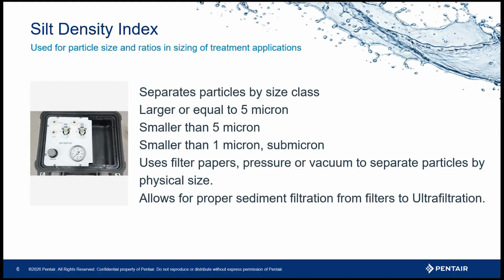Tannins are an interesting category of colored water to deal with. They tend to come from shallow wells or surface water sources where you have a lot of dissolved organics. This is the stuff that makes your red wine taste bitter, right? Depending on the amount of tannin in the water and the starting water chemistry, you're going to select different methods to address this problem. And this is where a full water analysis really helps in selecting solutions for tannin colored waters.